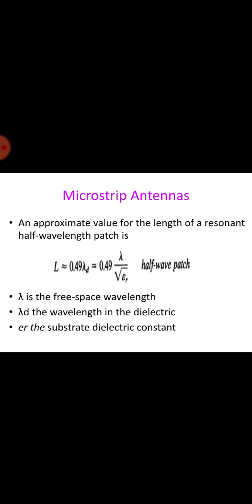Okay. In the rectangular patch antenna being fed from the microstrip transmission line, the substrate thickness T is much less than a wavelength. A rectangular patch is usually operated near resonance in order to obtain a real valued input impedance. Models are available for determining the resonant frequency, with the cavity model usually yielding accurate results.